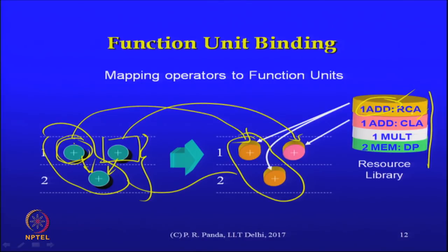Since there is only one adder, how is this supported? Only one add RC is written, right? Yes, but remember that I have scheduled some operation on that adder in the first clock cycle. In the second clock cycle, I am reusing that adder to do something else. That is all right; I still need only one component. I am reusing it in time, which is okay. In space, I can't reuse. If in the same clock cycle I need multiple operations to be performed, I need them to be performed on different components. But across clock cycles, I can reuse components.